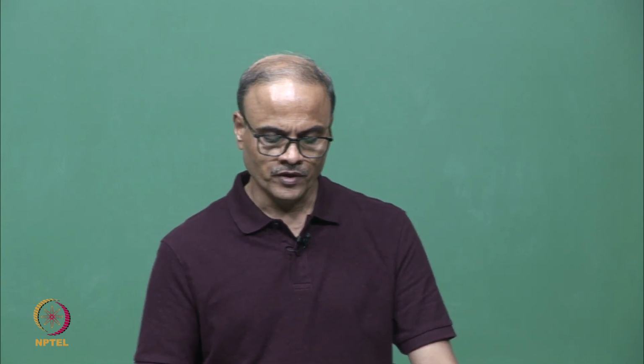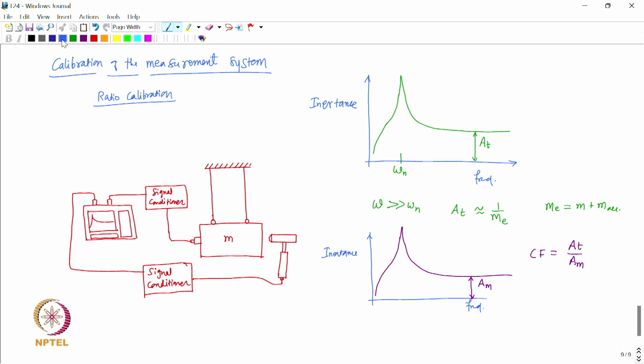So, let us say if we measure the FRF during a modal test, let us say we are performing it on a structure, let us say it is simply a beam structure, right. So, now we perform using this measurement system the FRF measurement, and let us say the FRF being measured here is, let us call that FRF as say A, right, A of omega.